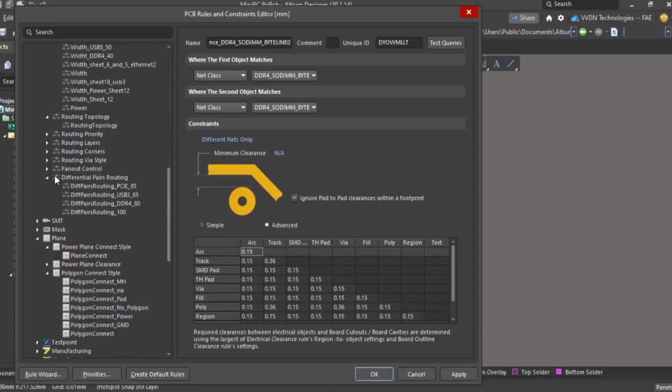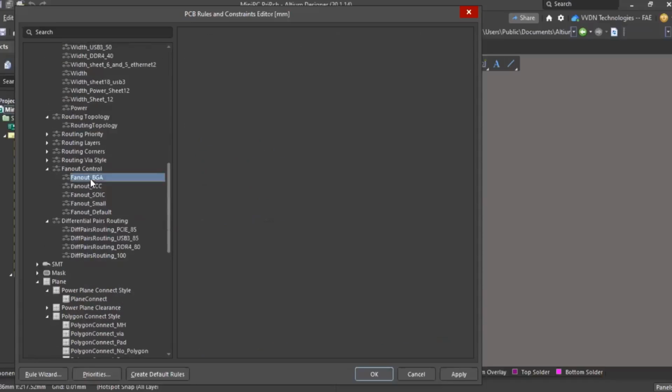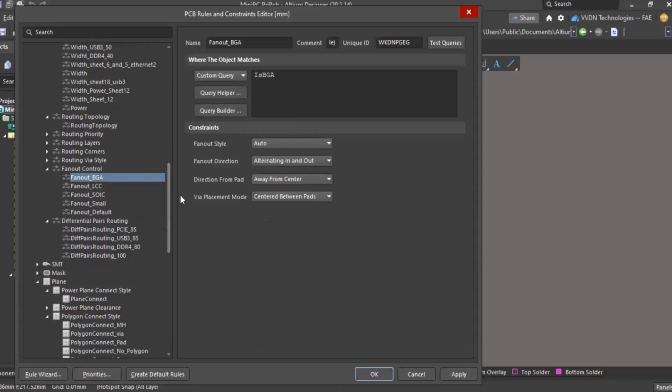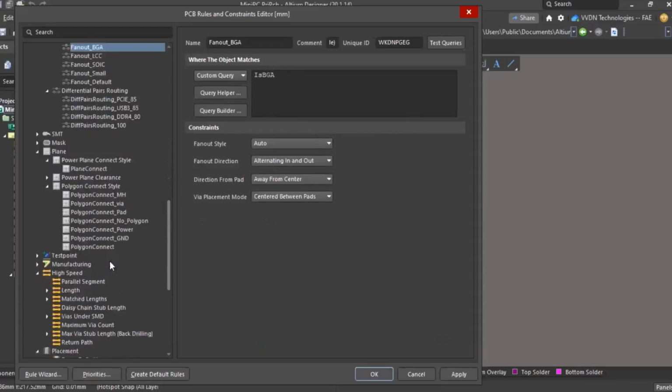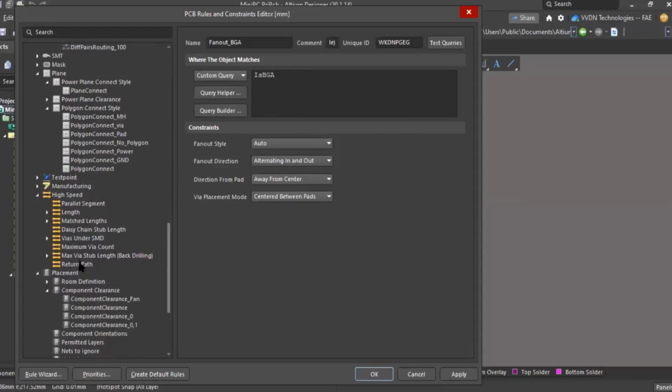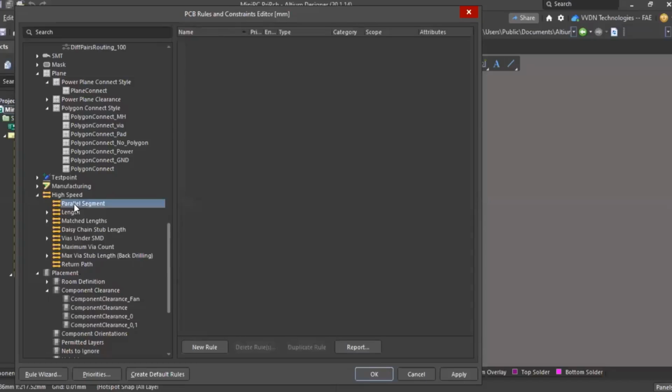some of the high-speed rules for fan out, again you can go with the default, okay? And if it is for a particular BGA, you can put a room over there and create a room for that. So these are the high-speed rules here. Parallelism, if you want to verify the signals, for example, worst case, you have 2 signal layers adjacent to each other, right?